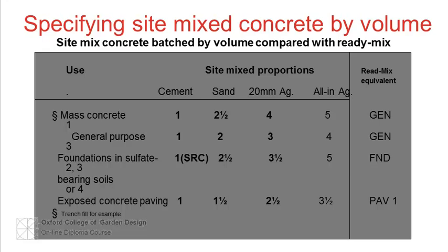For concrete that will be both wet and exposed to frost, like drives and paths, a proprietary air entraining admix should be used to ensure frost resistance and resistance to de-icing salts. This will automatically be included in the designated mixes obtained from ready-mix plants.